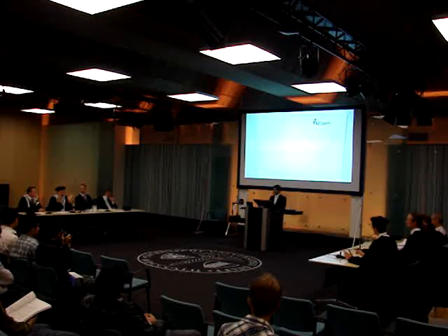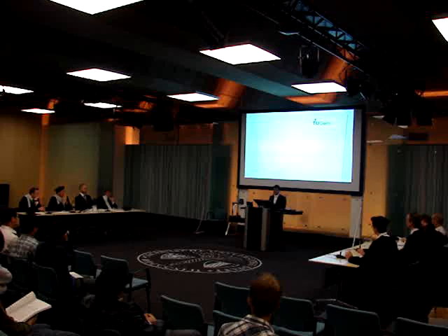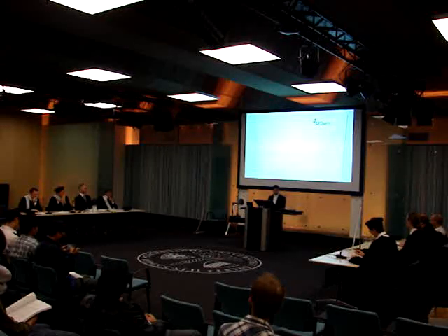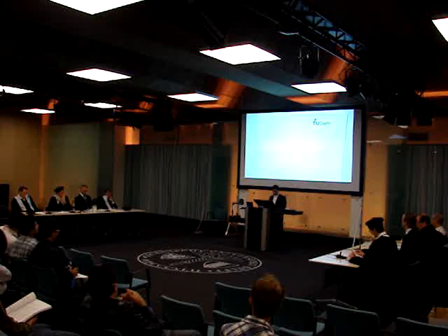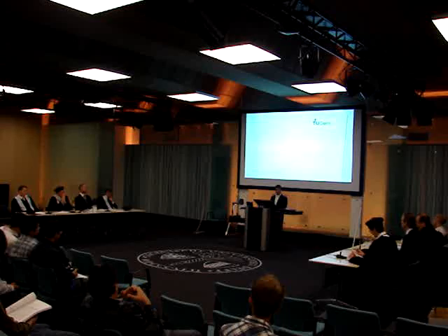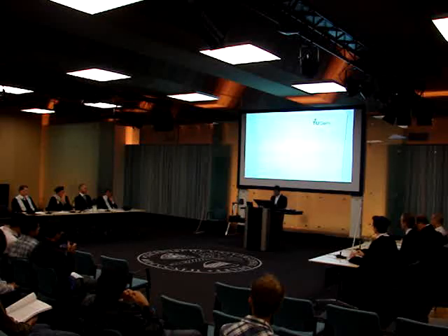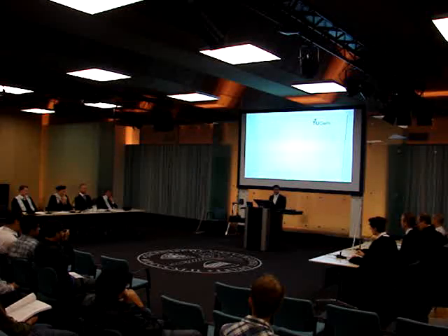Can you be a little bit more precise? What kind of difficulties? The difficulty is that the RVE, especially for random materials like concrete, should be large enough to contain enough of the heterogeneities, so that it is representative for the entire microstructure. But on the other hand, it must be small, so that the traction is uniform over it. So it should be large, but it also should be small to satisfy all conditions. That's the difficulty I'm talking about.